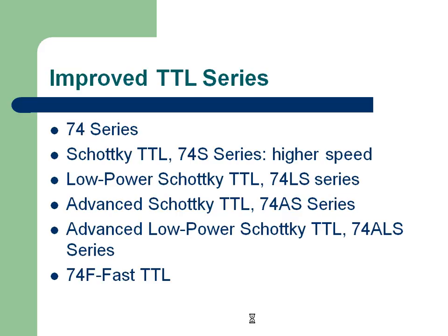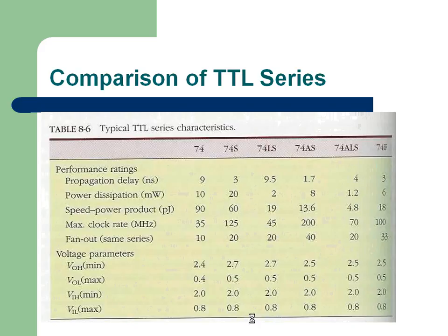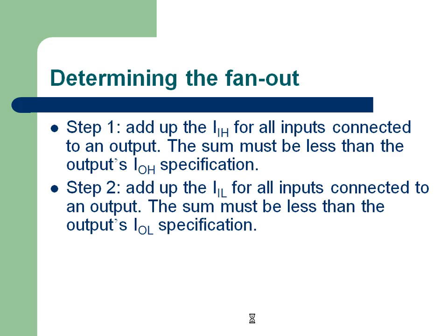In this context, for your reference, to understand the numbers: for TTL we are talking about delays of the order of nanoseconds and power dissipation of the order of milliwatts. That is the potential bottleneck of TTL. Whereas with CMOS, the delay would be slightly more, maybe 15-20 nanoseconds, but the power will be of the order of nanowatts. That is where CMOS becomes very useful.